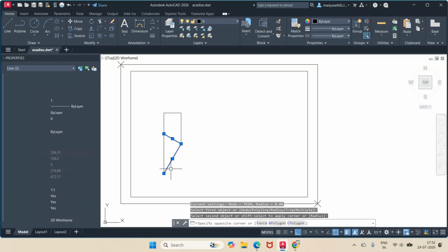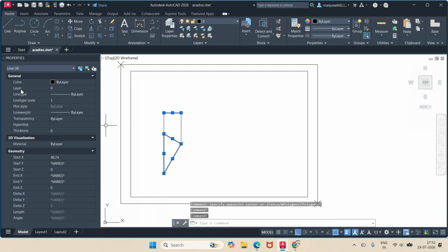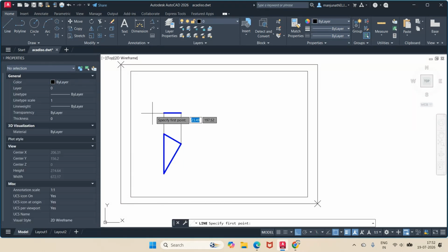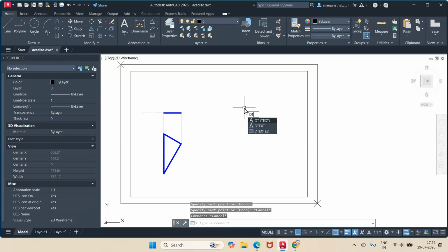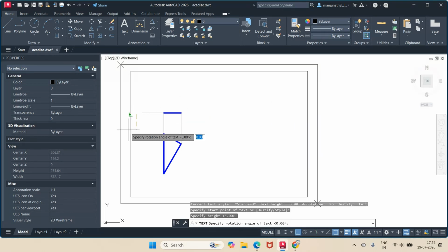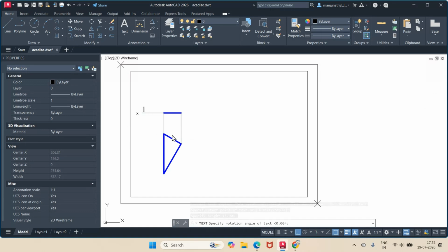Now I'll select all the front view and top view, go to layer, move to visible line. Then I will draw a line from intersection point and I will take this to the next line. Similarly, I will go for the text, select this point and put the caps lock on, to the height of 33.3 mm, go to VP and similarly with respect to HP, and here you type capital letter A, B, and C. Similarly, you take A dash, then B dash, then here C dash.